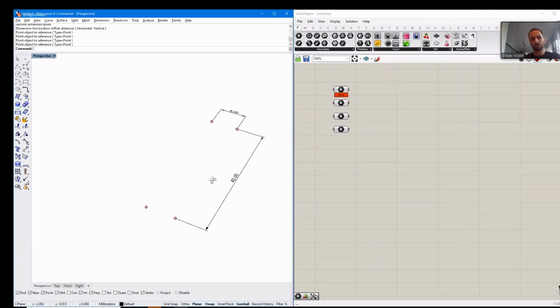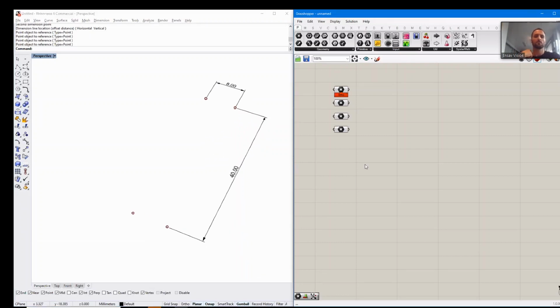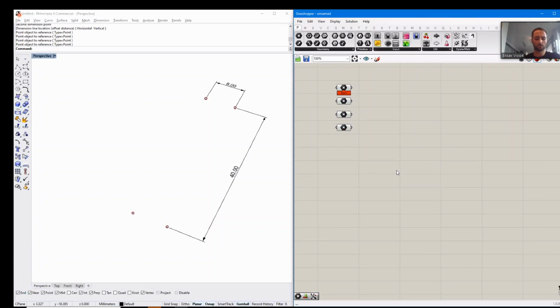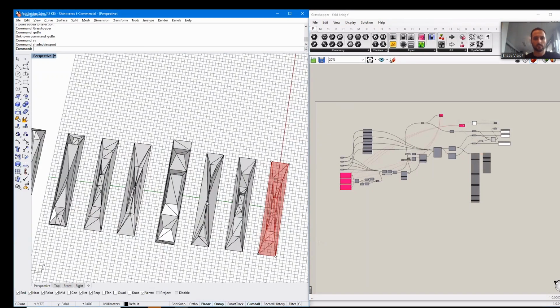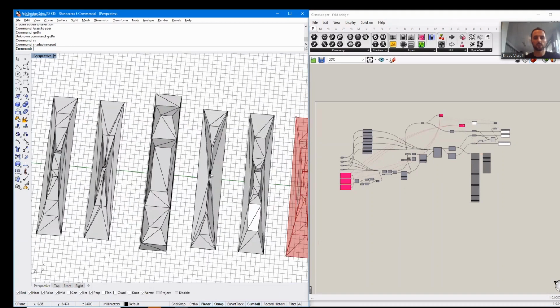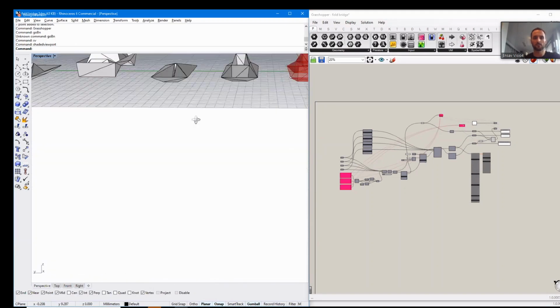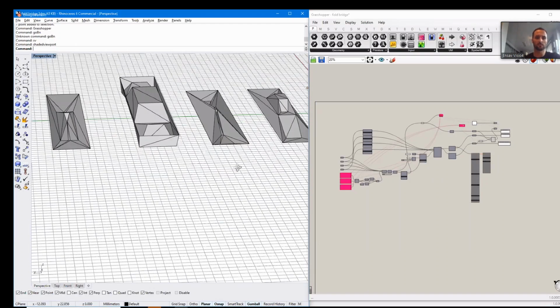And the main technique how we are going to produce this bridge design is by using a Delaunay triangulation mesh on a set of points we generate. So these 4 points are always there, always will be given, the 4 support points, and we're going to create 4 other points which we parameterize in their position and then mirror them 2 times along the longitudinal and the transversal middle axis of the bridge. So we have kind of a symmetric design output, which makes a lot of sense for a bridge.